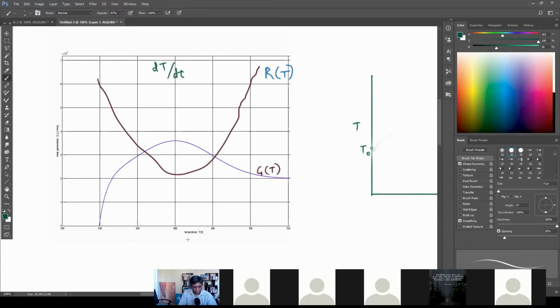And you see down here, we have temperature. So if temperature is increasing, then we are moving to the right here. And if you consider the relationships here, if your rate of removal of energy is more than your rate of generation of energy, then you are on balance removing energy from the system. You are reducing your thermal energy.